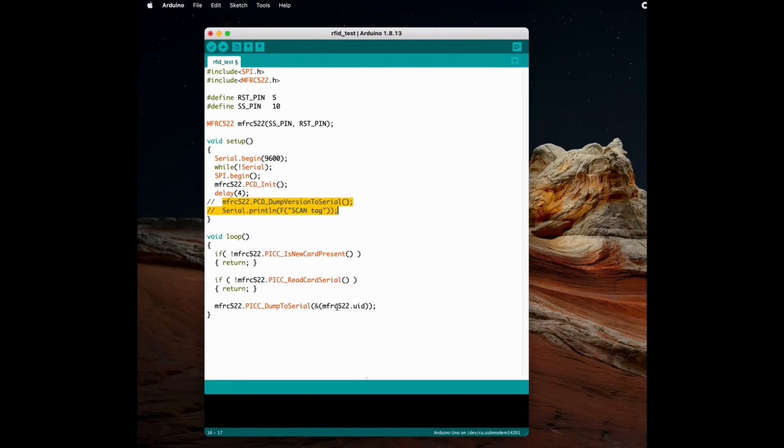Now that we've learned how to identify a given RFID tag, let's try and see if we can implement a system to utilize the UIDs of these RFID tags to, say, open a door or any kind of security system. Now using the same code, we initialize content and letter to obtain the ID of each tag that is being detected. To obtain the UID, we need to go to the 0th byte and concatenate the characters in those bytes.